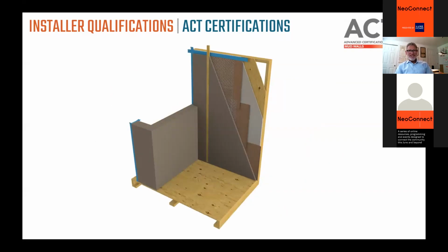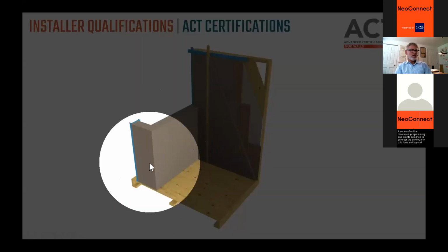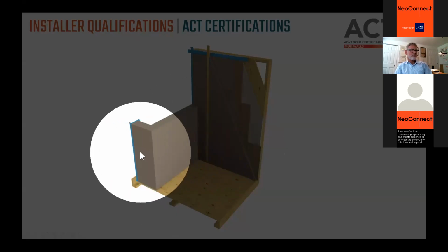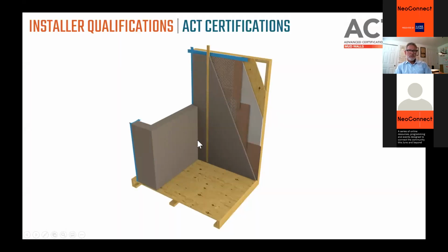Mud walls, essentially the same skill set on a vertical surface, with the added caveat of the inside and outside corner. So we have to be plumb here at the inside and outside corner. We also have to be dead on our dimensions. So from finished mud to finished mud has to be no more than a 1/16 of an inch off, because in the real world, it matters.